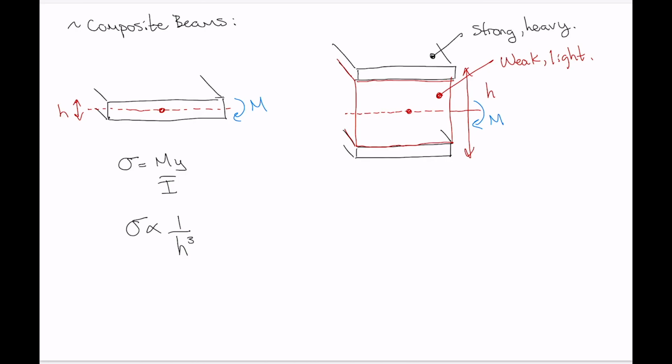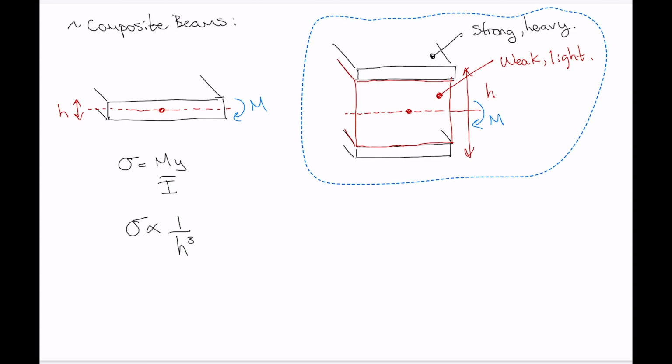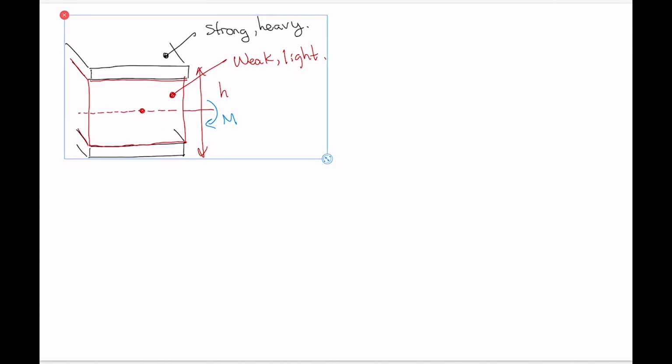In order to calculate stress in a composite beam, we imagine transforming that composite beam to an equivalent beam made of only a single material. Okay, so I'll show you what I'm talking about on the next page here. We'll just grab this drawing here and flip over and paste it back here.